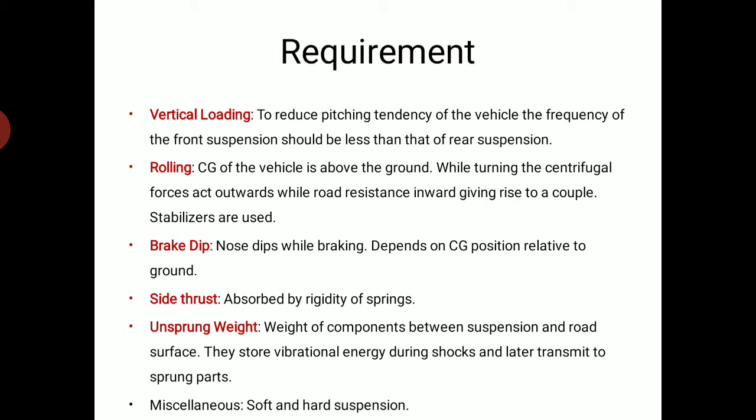So this is very important. Rolling: already I told you, the center of gravity of the vehicle is above the ground. While turning, the centrifugal force acts outwards, while road resistance acts inward, giving rise to a couple. Stabilizers are used.